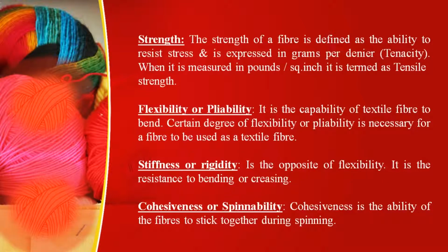Moving ahead, we have some more terminologies. Strength. The strength of a fiber is defined as the ability to resist stress and is expressed in grams per denier, tenacity. When it is measured in pounds per square inch, it is termed as tensile strength.